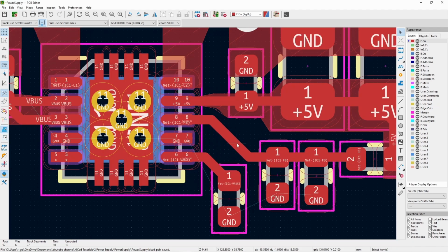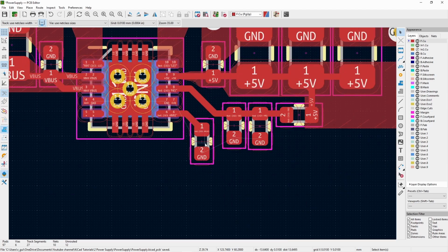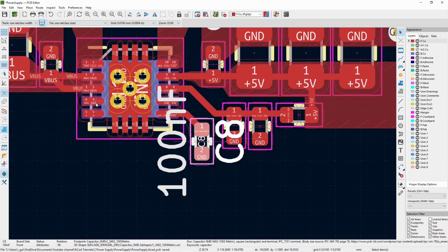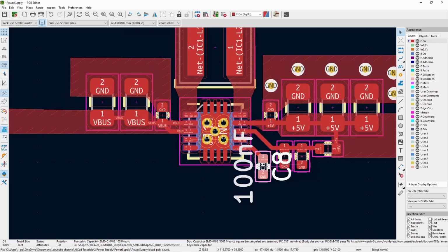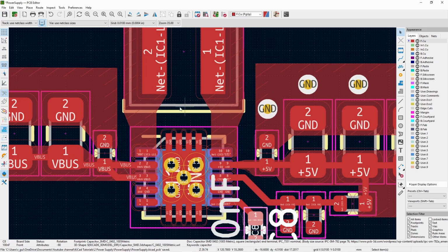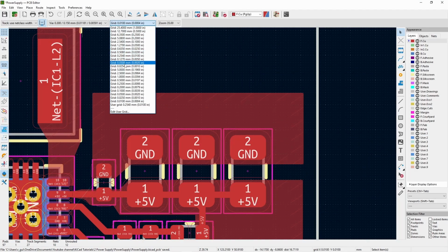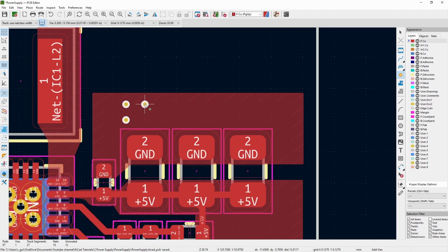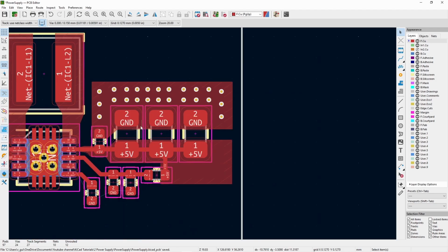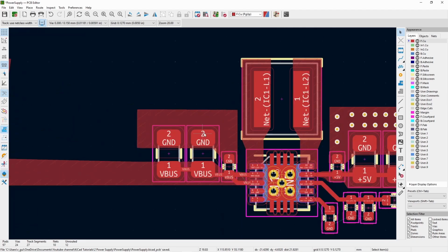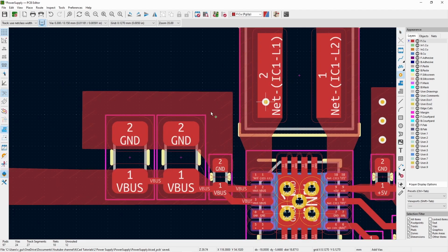Now you can see I need a few more connections on this. One ground connection here, I need a ground connection there, and then I need to connect all of this to ground as well. Now that might be one too many wires, but that's alright. So you can see that's nicely connected to the ground plane. I'll do the same over here. Might not go as crazy.